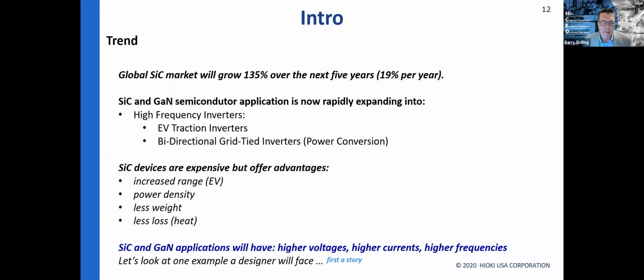One of those includes the current transducer, sometimes called a CT. In the past, they were transformers. Less and less they're transformers, and they're more and more transducers, as in the FluxGate device that we manufacture. But the old school clamps were called Hall effect. They had a lot of bandwidth, reasonable accuracy, not the most accurate CT, used to some degree with scopes.